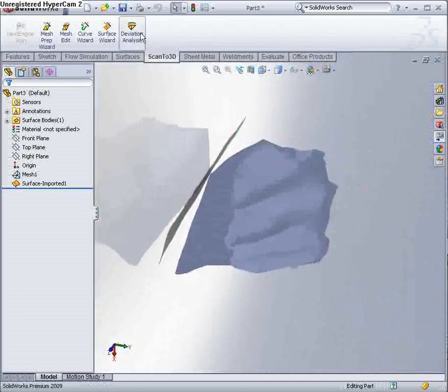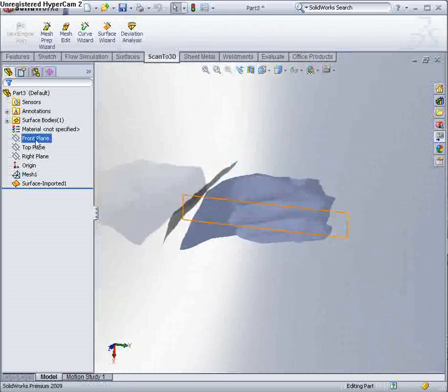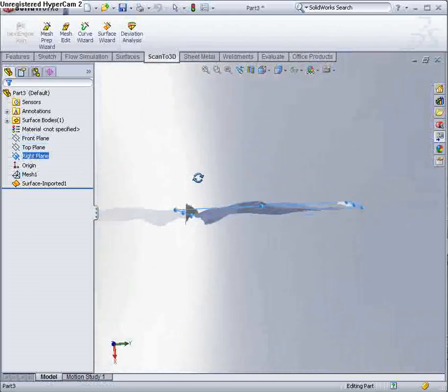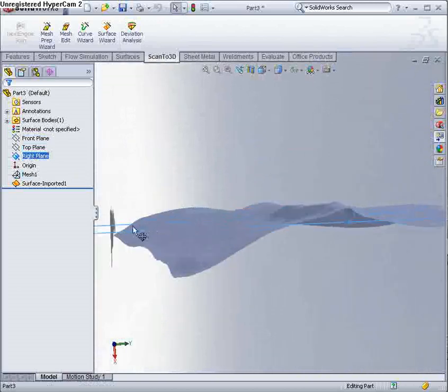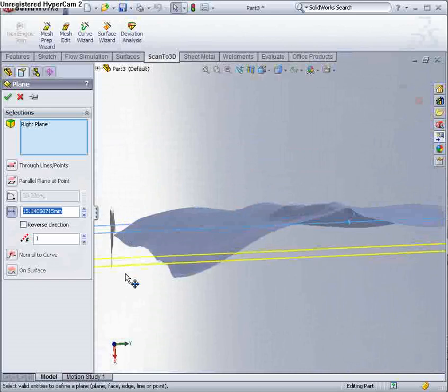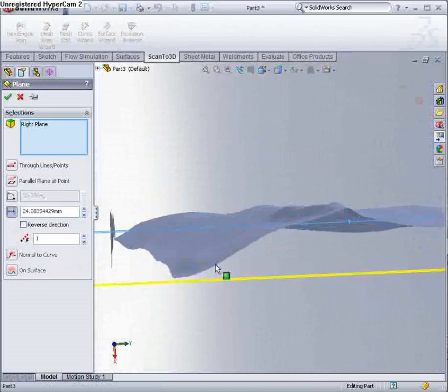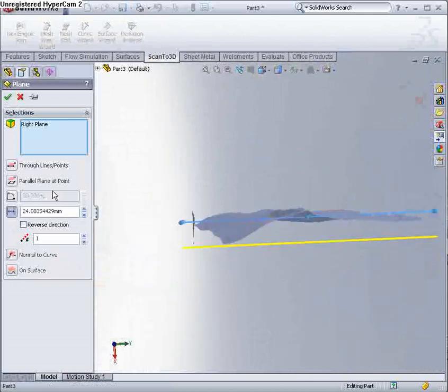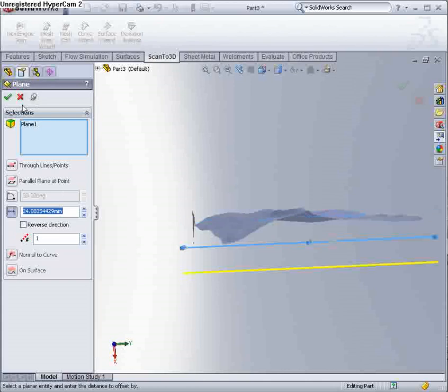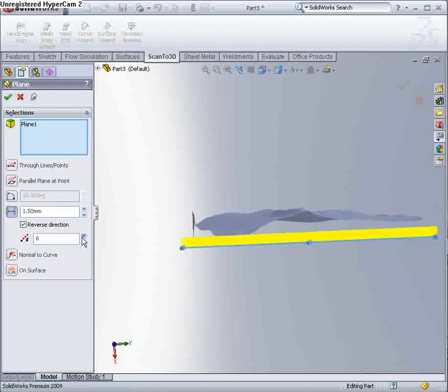So what I want to show you is creating a topographical map from this model. So what I'm going to do, I'm going to copy down this plane to just below the model. I'll pin that command, we'll leave it there, and I'm going to make these. Don't want too many of them just because it takes a little bit longer to process. So 22 planes, so each of those intervals, so you can specify where you want them. We're going to make a